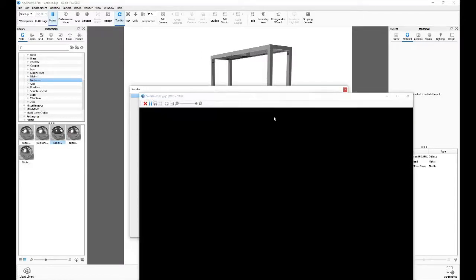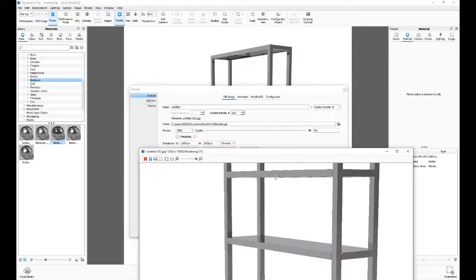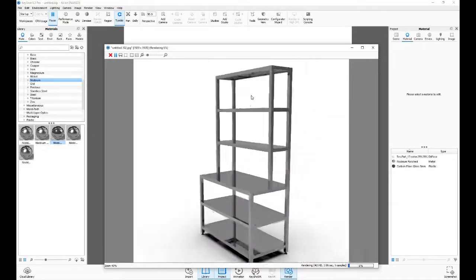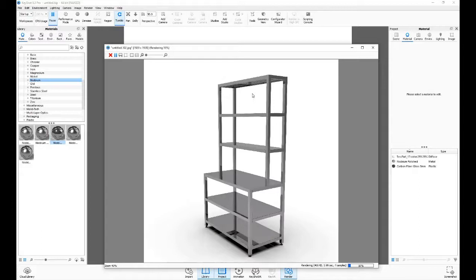Next I'm going to go ahead and preview this real quick. So on the configurations, I'm just going to kind of walk this down. So I'm going to uncheck the edit. I'm done with the file names. Check on the configurations. Then I'll hit next. So on the configuration, we'll just double click on the universal beam. And for the inputs here, I'm going to set this to safe working load and go ahead and hit OK. And we'll do it again.